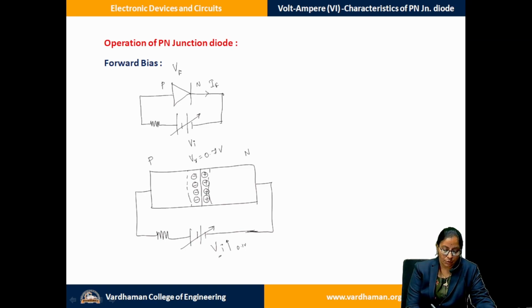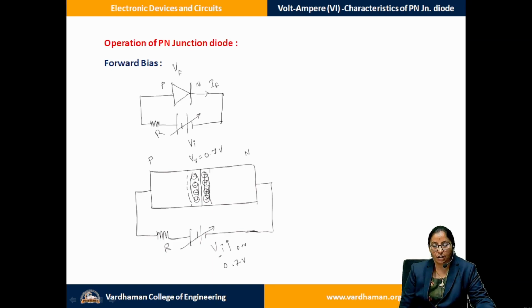This is a simple series arm resistor R we are taking, and as we apply a potential of around 0.6 to 0.7 volts, which is for silicon, if a silicon diode has been taken up, the depletion layer present on either side gets completely nullified, and you see that the barrier is ready for the conduction of majority carriers. Once this depletion layer becomes completely zero, we'll see this.